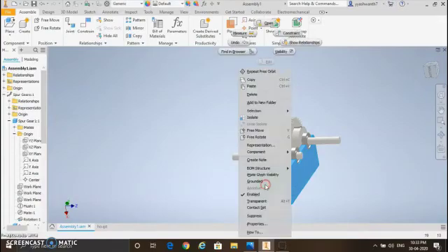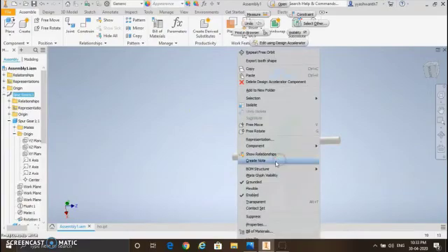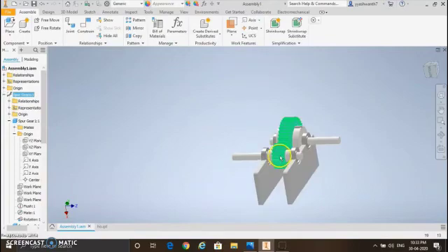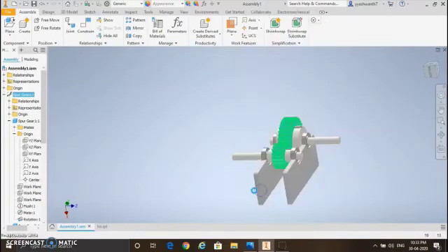As you see, the design of the gear train and housings are finished, and we must see that the housings are grounded so that they are not rotated, and make the gears flexible and disable the grounded option so that they can rotate on an axis.